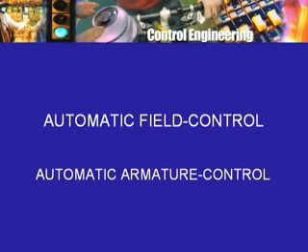And this is where the earlier classification of speed control of a motor into field control and armature control will come in. The operator can adjust the speed by changing the field current. Now instead of the operator adjusting the speed, you could have an automatic device or controller in which these adjustments take place. If that is the case, then we are looking at field controlled DC motor. And as I said, this is one way of controlling the motor, not by manually changing the field current, but by automatically changing it or adjusting it. This is field controlled motor.